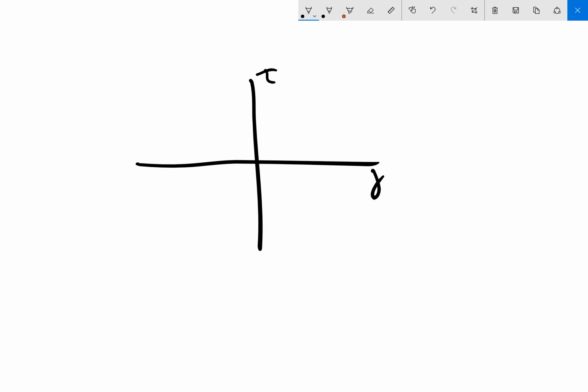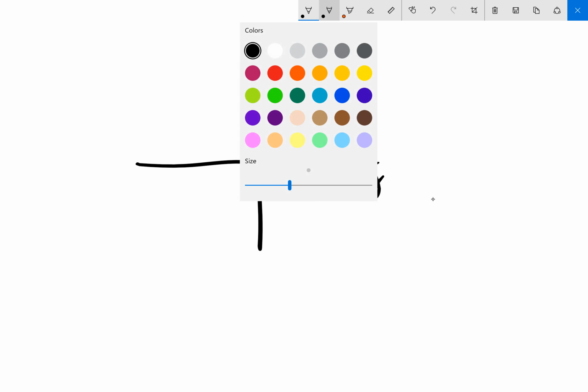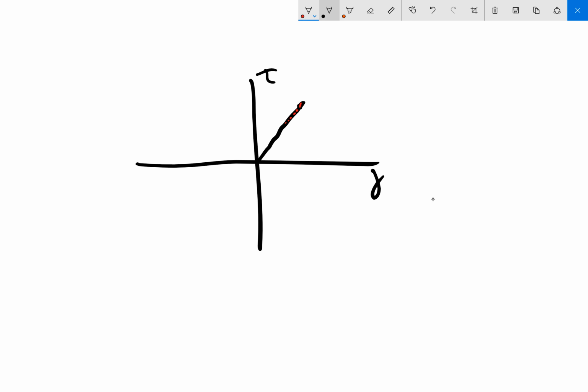Loading and unloading rules refer to, if I have strain and I have shear stress, if I load up and strain a soil and then I reverse direction and I want to come back down, is it going to follow the same path down, or is it going to come down at a different stiffness or a different slope of the line? That's what we call loading unloading rules.